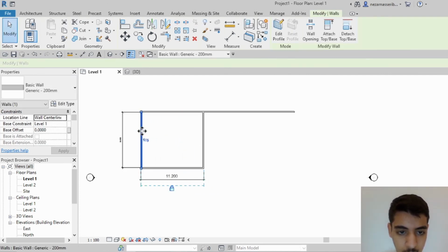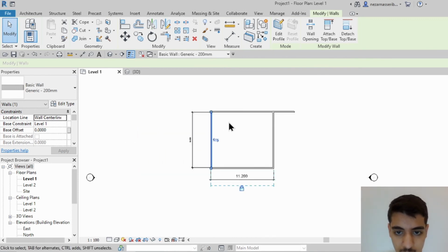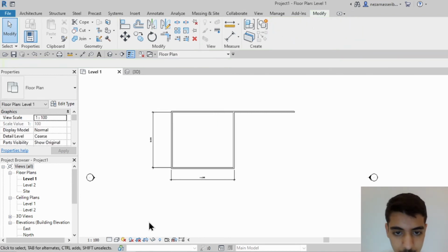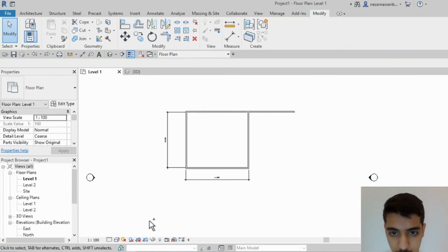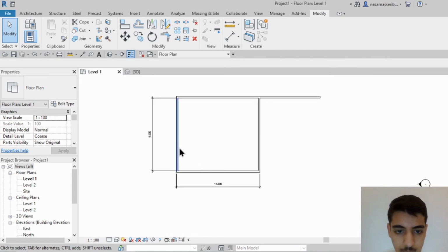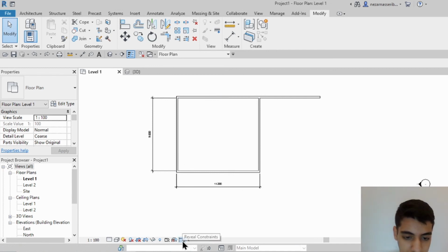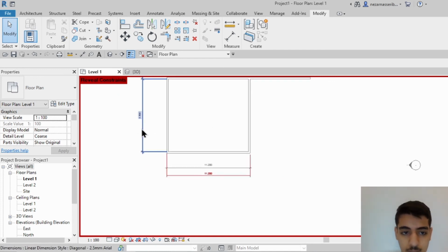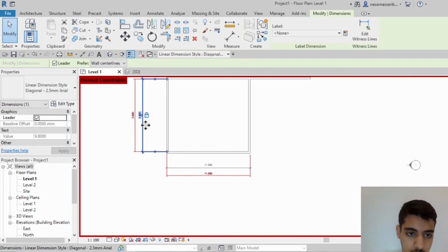It moves all the walls together and changes the size of this wall. Changes the size of this wall right here. See? And this is what constraint means. I'm just gonna take that back to normal really quickly. Yeah. And then if I want to see what constraints have done, I can click that, and it can show me that this is constraint, but this is not constraint, and I haven't constrained that yet. But I can click on it and constrain it whenever I want, and it's just added back now.